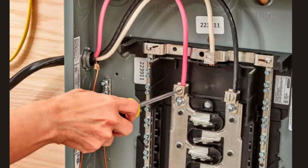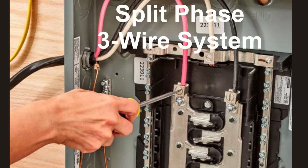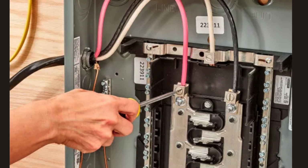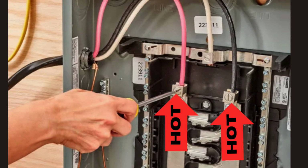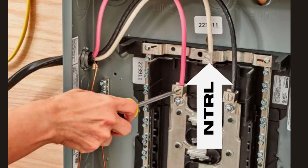We should take a minute to discuss this system. We are assuming a split-phase 3-wire system here. This is a typical power supply for residential and light commercial applications in the US and Canada. The service consists of 2 hot wires and 1 neutral.